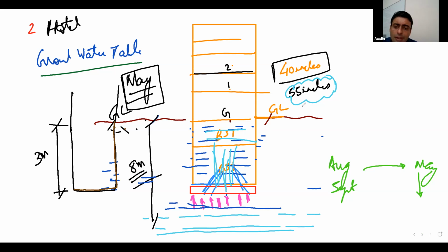If you have visited any farm where you have black cotton soil, you will always see very large cracks over there. You see large deep cracks in the months of summer. If you go, these cracks can be as deep as 600 to 800 mm. So black cotton soil has this problem that it swells under moisture. It has a large swelling potential.